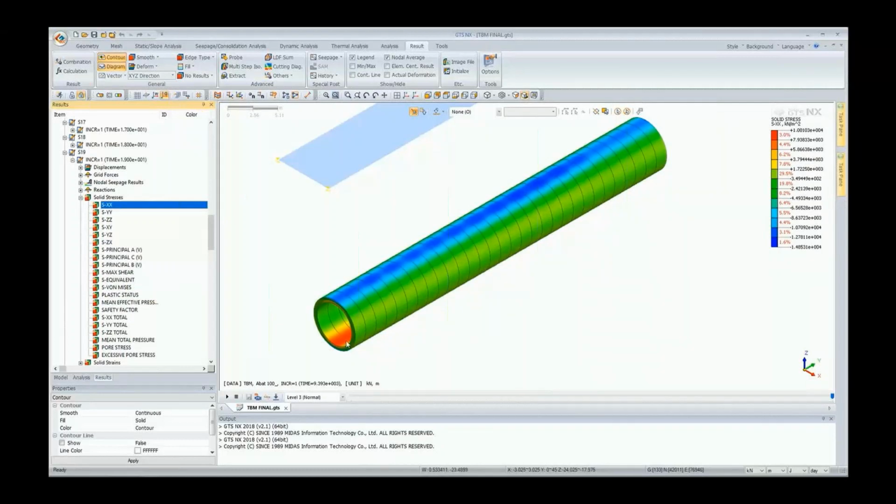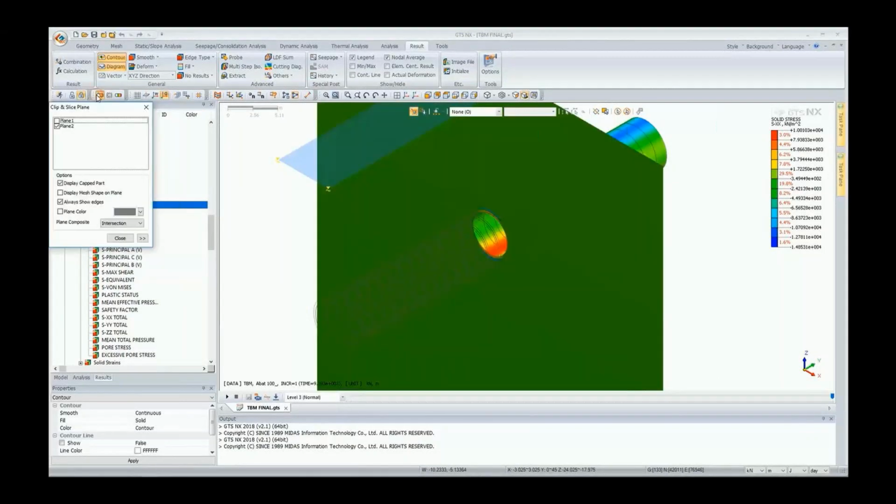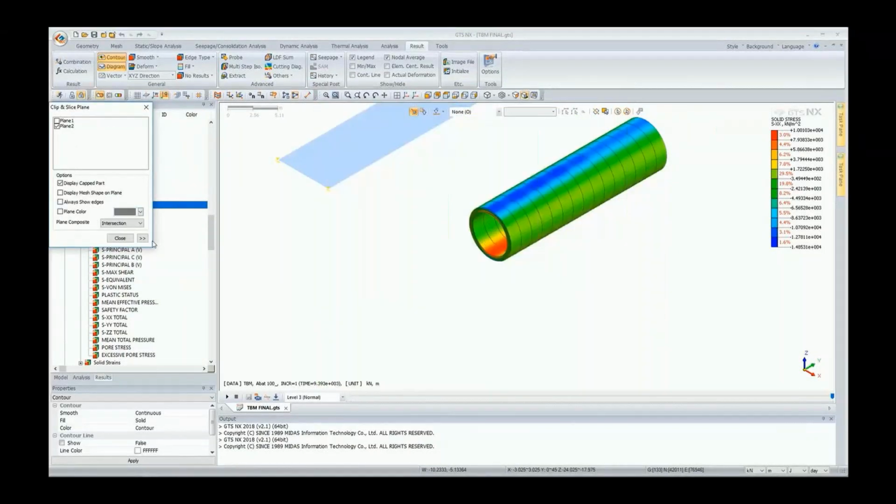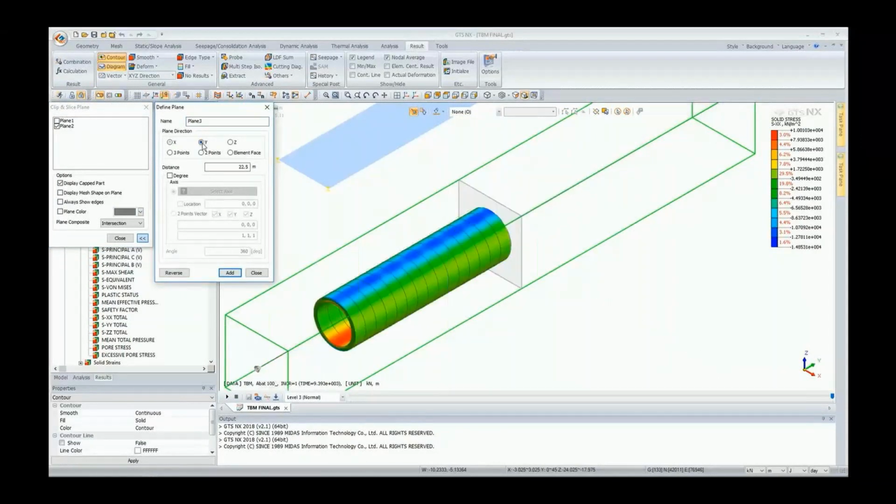And now we see, in this case, that we have the tensions, or the positive red, in the inner face of the secondary support. And then we have compressions, or blue negative values, on the outer face of the primary support. And this is opposite to what we're seeing in the vertical stresses. So now I'm gonna do a cut of my model to look at the results.